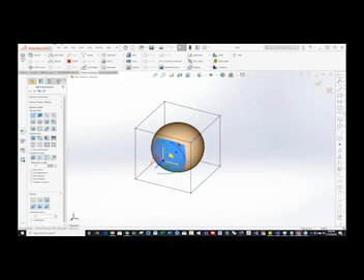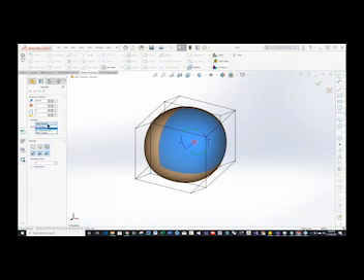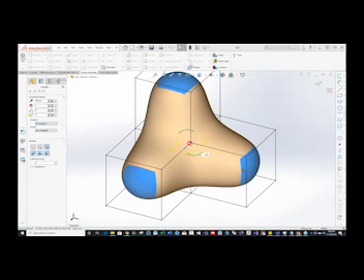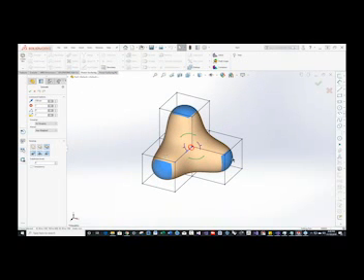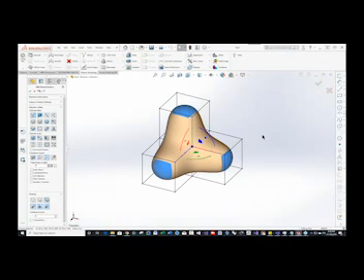So let me make things a little more complicated here. I'm going to grab 3 faces and I'm going to extrude them, and I'm going to say no grouping on the edges, so it gives you the individual faces extruded in their own normal direction. And so now we've made it more complicated, and we've created a more complicated topology. For example, if I extruded this one again and over and up, I could create a little ring or a loop there if I wanted. So let's explore what we can do with this thing.